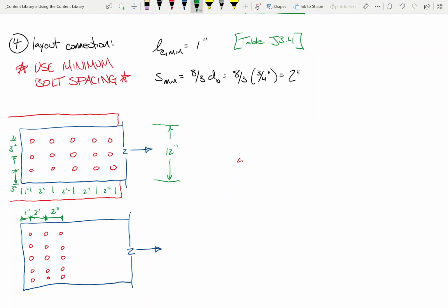Yes. Okay? So you said 16 bolts. A 16 bolt pattern would be 4x4, right? So a 4x4 pattern might make sense if we don't fail spacing and edge distance limitations this way, right? We couldn't do this if the space between bolts was like ½ inch. That wouldn't make sense, right? We still have to meet edge distance requirements and spacing requirements all around because they have nothing to do with strength, right? So we can lay out the connection any way that we want, provided we meet these limits, okay?